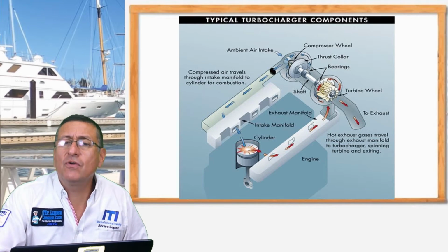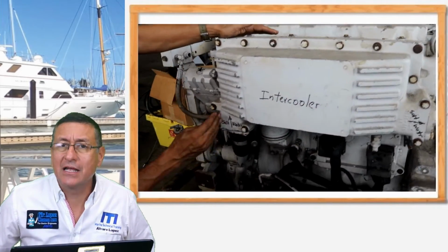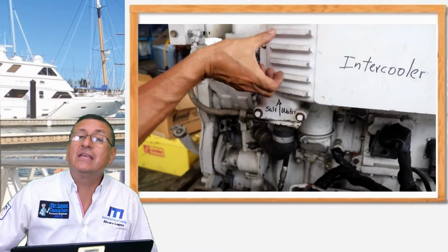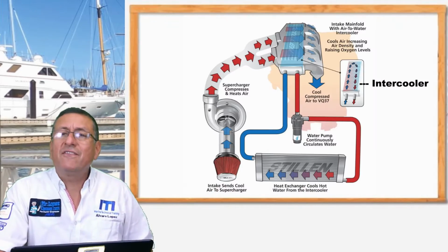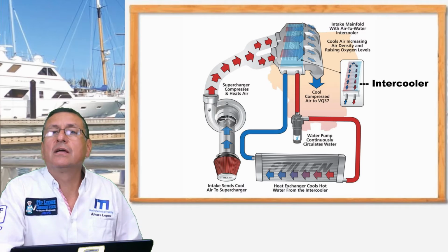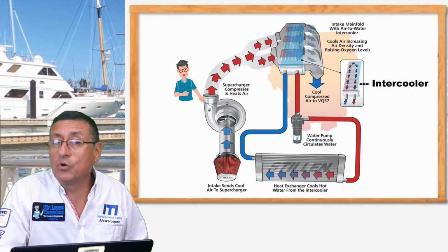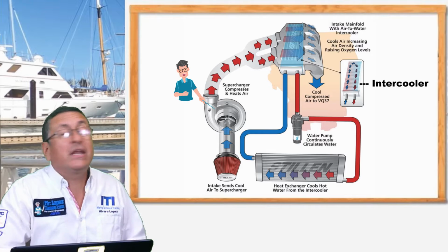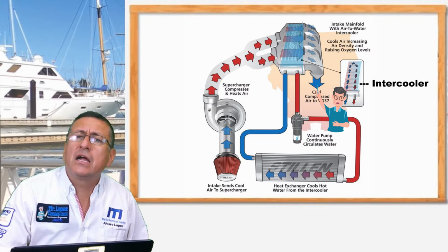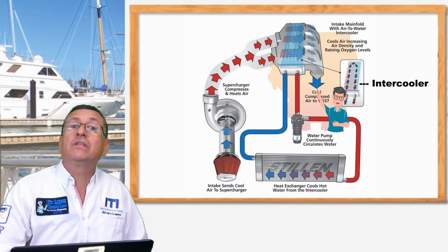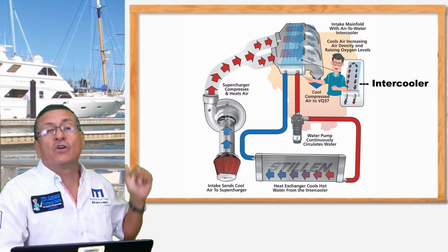And check, if you have the chance, one engine with the intercooler and verify how is the flow of air with the intercooler. Verify in a typical intercooler where is the input of air coming from the turbo or the supercharger and where is the output of the air and how the air is cooled. With salt water. Where is the input of salt water and where is the output of salt water?